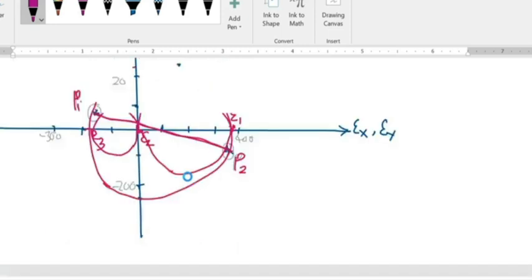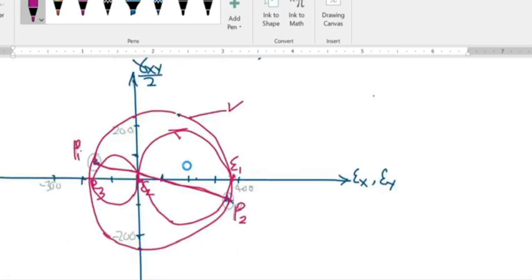So you can also see that this angle corresponds to also this, because this is the angle you need to tilt the initial complex strain to be able to arrive at the maximum principal strains. So this is the same angle, which is what? 9 points. You can also see from here it is negative, minus 9.55 degrees. So this is the orientation angle. It means the angle you need to orient your complex strains to arrive at the principal strains.